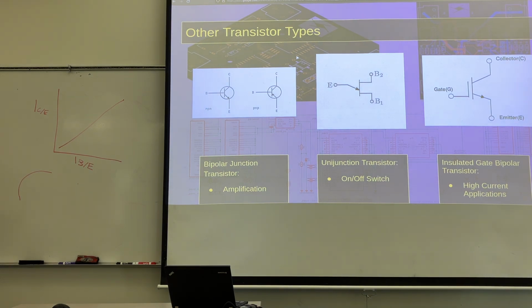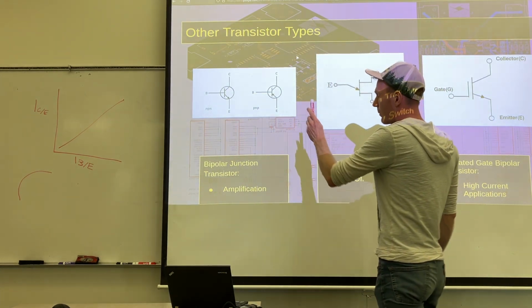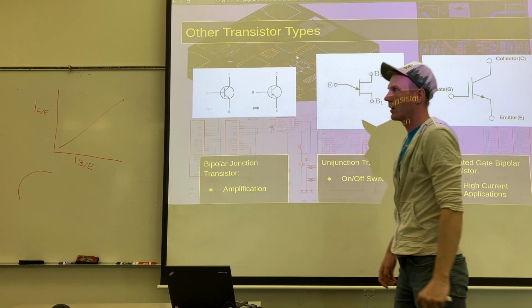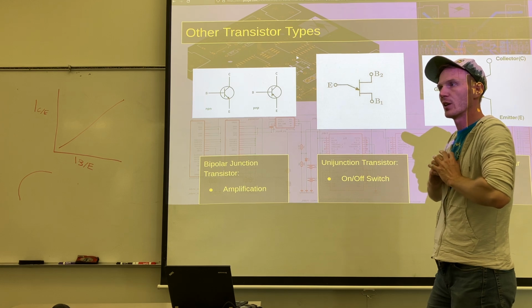Each one of those is a different transistor, and all you're doing is modifying the gain by selecting some biasing there, which basically says I want it to multiply by 2, I want it to multiply by 4, I want it to multiply by one half. So the schematic in that case is a whole bunch of these with some variable resistance that you can set remotely. So yes, we will see these in a circuit here because their linear relationships are very useful to us, but a lot of it is MOSFETs.